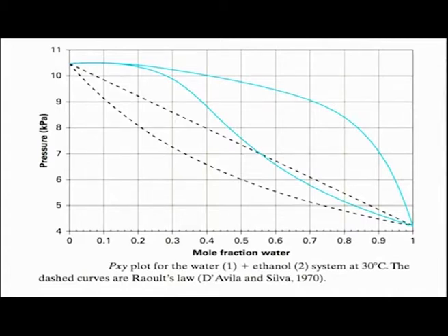If you had used Raoult's law, of course, it shows that this system pressure is between the dew point and bubble point pressure, but in reality the system pressure is below the dew point pressure, and that is the reason that the work which we did will not be realized in reality. It will flash completely, going from liquid to vapor. Which essentially means that, knowing that water and ethanol is not a very simple system, it hydrogen bonds also, we went ahead and used Raoult's law as a model, which was in fact not appropriate.